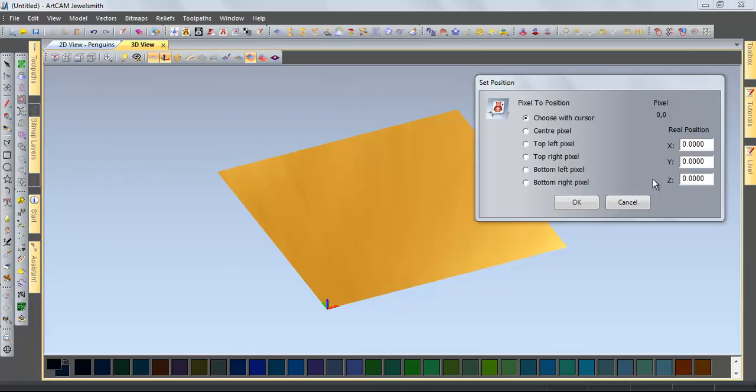The important point here is that your Z value should be at 0. Especially the Z should be at 0, because it should not be at negative or positive values, in order to avoid any problems during cutting while tooling the model you have made in machine tooling. In one case, it will cause the machine to wander idle during cutting, in the other case, it will cause the machine to cut more depth than the desired depth and cause accidents such as the head and blade breaking, the head hitting the material.